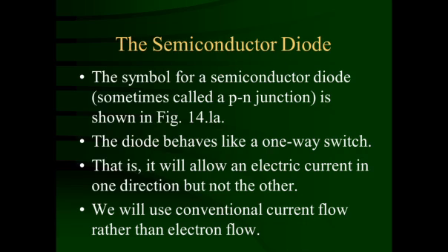And in a diode, normally when it is forward biased, current is flowing. That means the anode is p type material, and the cathode is n type material. So the p type material is connected with the positive terminal of the battery, and the n type material is connected with the negative terminal of the battery. Then it is called forward bias. Then the current flows in the order of milliamperes, and it follows a square law diode characteristic. So the current is very high, and the voltage drop across the diode when forward biased is 0.7 volt.